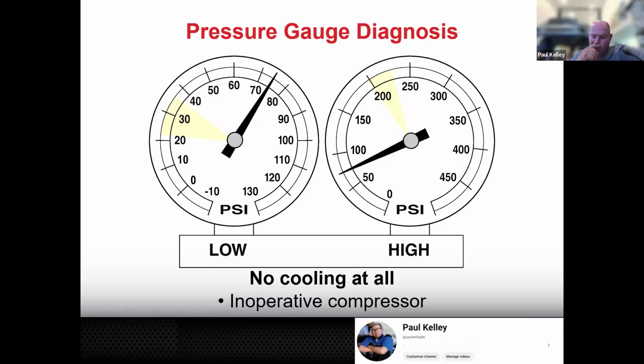That could even be a temperature sensor or switch, a pressure sensor or switch. There could be a lot of stuff that would cause the AC compressor to not engage, whether it's the solenoid for variable displacement or the compressor clutch, right? So remember one of the earlier things I showed: look down there at that compressor. If that compressor's not on, you figure out why that compressor's not on. You don't start selling stuff.